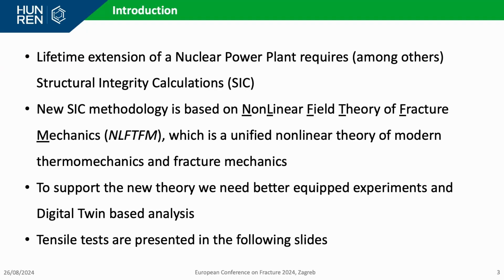So our institute is involved with the lifetime extension of the Hungarian MPP called PAKS. And our research group performs structural integrity calculations. This new SIC methodology is based on nonlinear field theory of fracture mechanics.